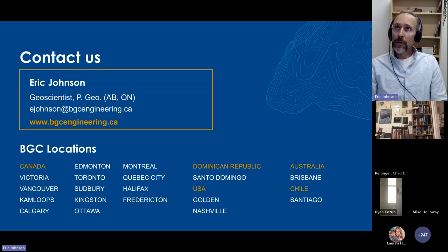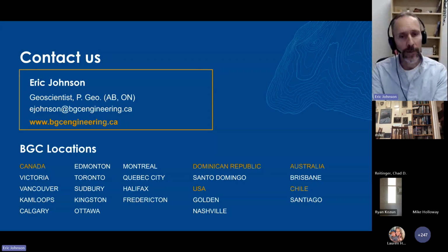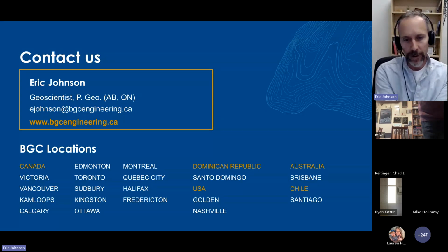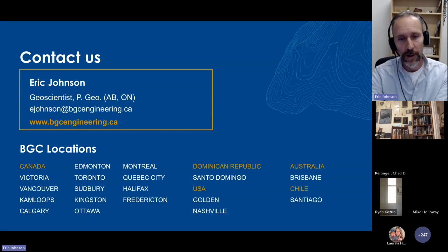With this one, this is something that could actually help with other sites. We've already started building a database across Africa with some of these samples. What we want to do is build various categories. Once we have, say, a certain weathering grade, we'll keep accumulating ERT values and seismic values for that.